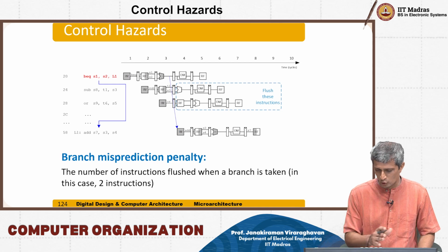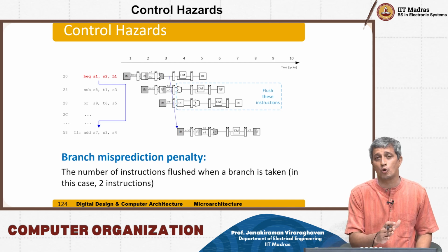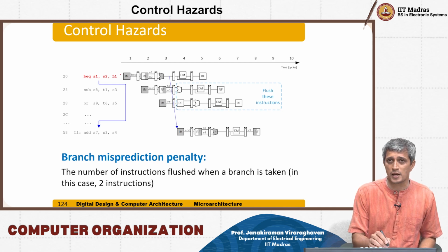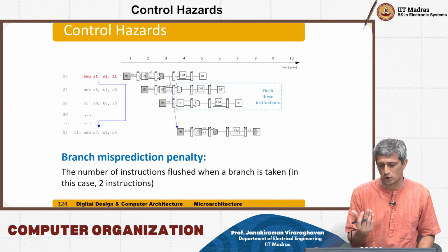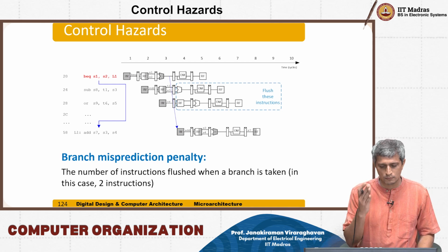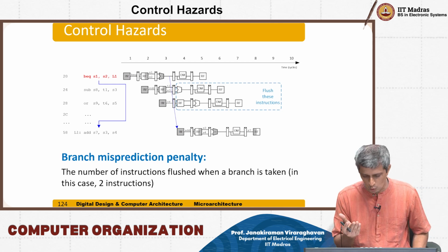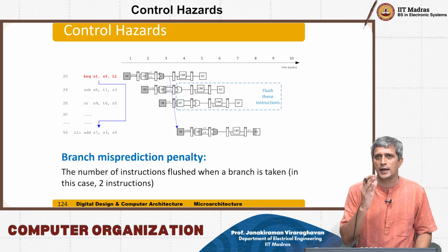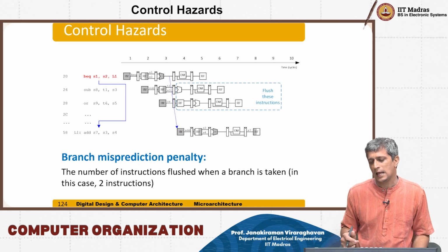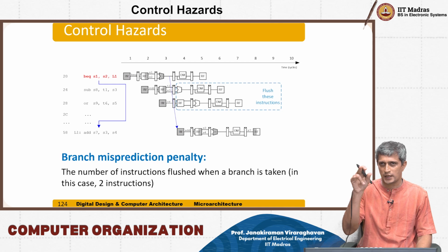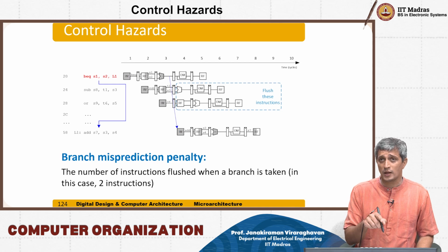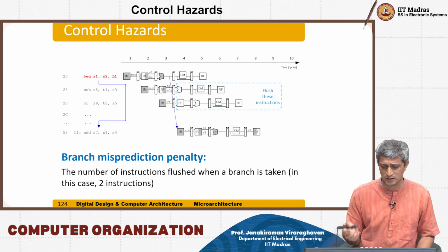So what is going to happen if you look at the sequence of these instructions? We know this timing diagram pretty well now. From the instruction memory you have fetched the branch on equal. The decode stage is now going to decode S1 and S2 for you, right? And the contents of S1 and S2 will be read out and given to the ALU to perform a subtraction operation. And that's when the zero flag bit will get set at the output of the ALU, right? And then you're going to go to the data memory and register file write back.